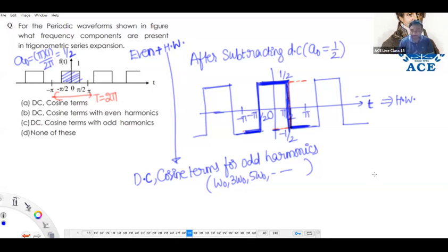See, one segment is like this. For that, we have done amplitude scaling. After that, that red signal is left shifted by half period. If you make a left shift of half period, we are in a position to observe the signal from minus pi to minus pi by 2. So it has 100% half wave symmetry.